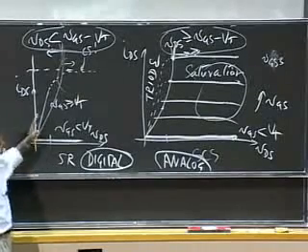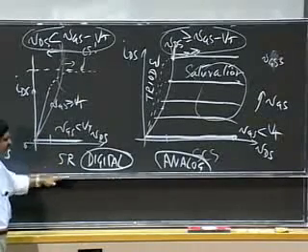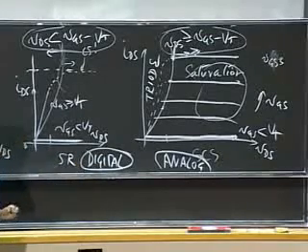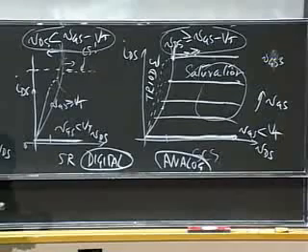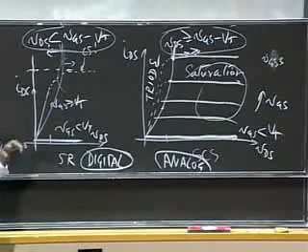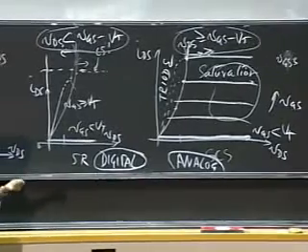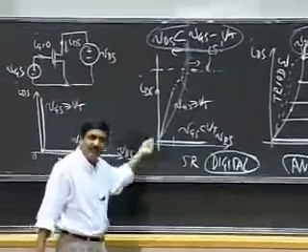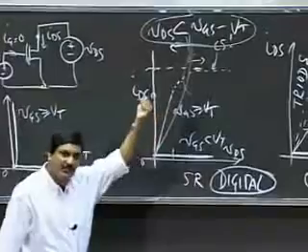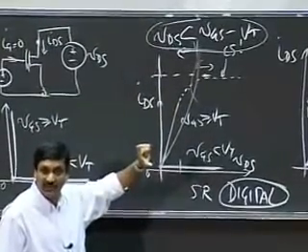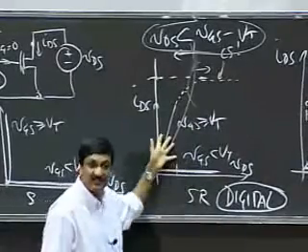And for digital designs, we'll simply use the SR model. It turns out that this is realistic because in the digital designs that you have seen and will be seeing in this course, when the pull-down MOSFETs are on, the output voltage is pulled down close to ground. So VDS is very, very small. So it does make sense that this model applies.